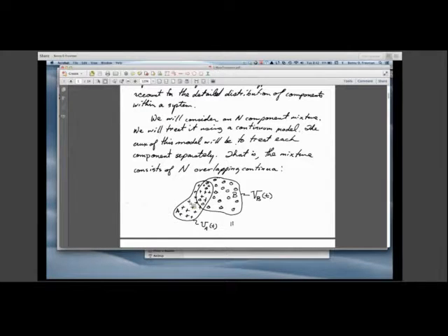It is a volume of material, and the thing that's special about a material volume is that if we draw a material volume around absolutely every molecule of A, where A is the little pluses here in this mixture, this material volume contains each and every one of the molecules of A that are in the system, and it is absolutely impermeable to A. So an A that is in the material volume never leaves.